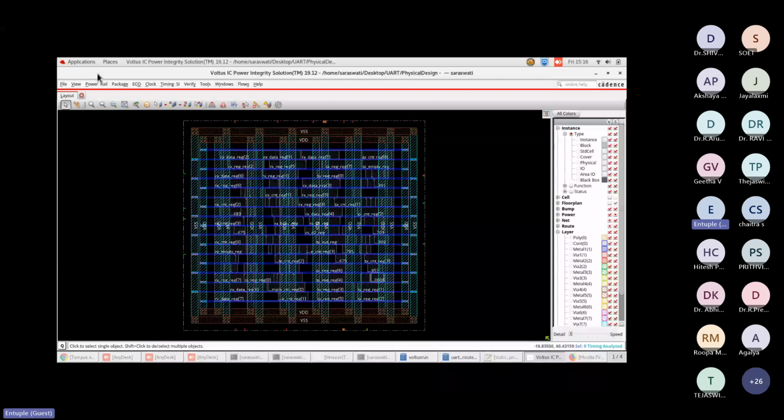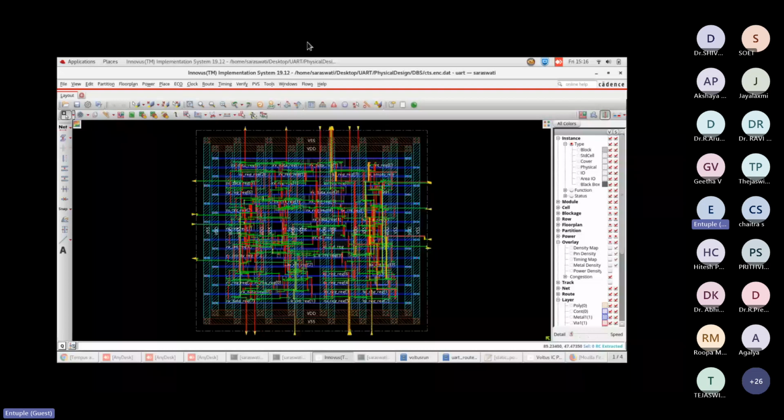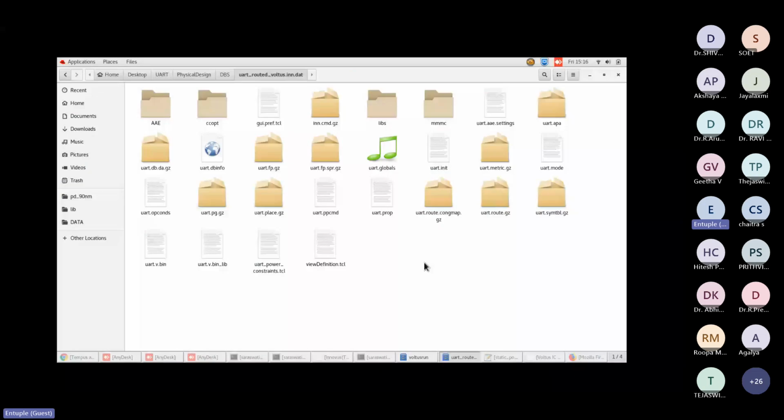to this entire data, the extracted data, you can pass to Voltus. Then Voltus is going to read the entire files, and then it will give the power report in detail. So it is basically optimizing power. It depends on the planning, like iterations, and you need to first give the importance to timing or power. So if it is power, you have a separate flow for power, a low power flow, or in that case you can avoid the performance related constraints and all.